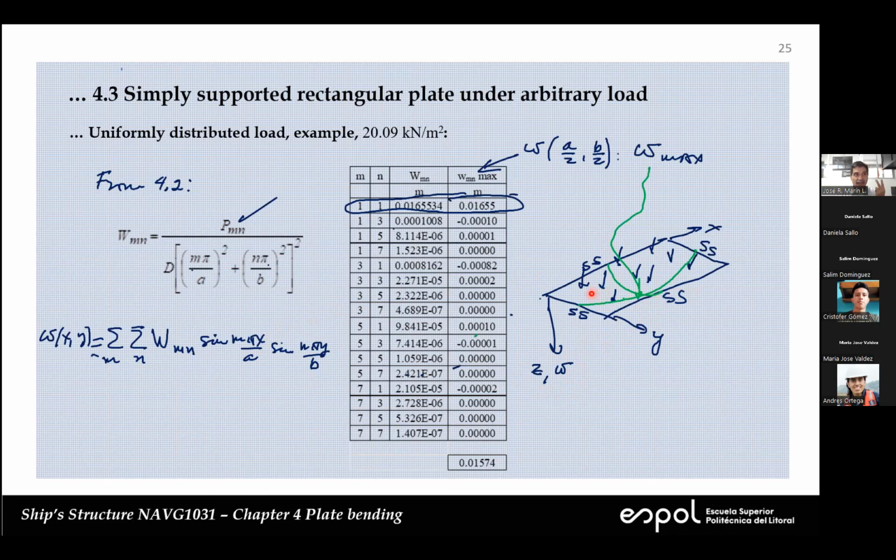Now, the second derivative gives you the curvature. In this case that I'm drawing here, you see that it's open upward. So the curvature will have one sign only. So we can expect the bending moment to have one sign in general, because it's open in that direction. Okay, this is a simply supported case. It's not just a matter of calculating something. There's a lot of information that we can deduce from these results. That's what we call analysis.